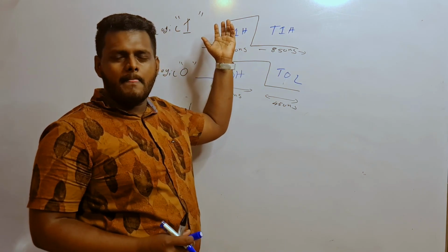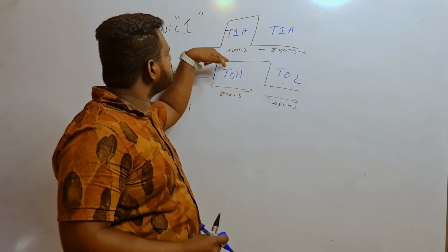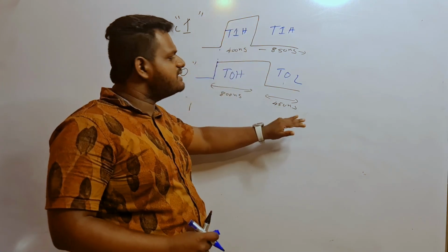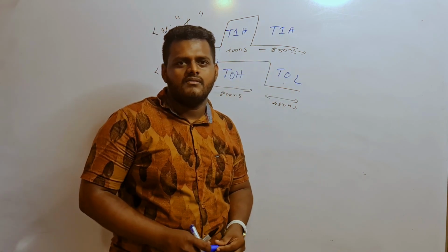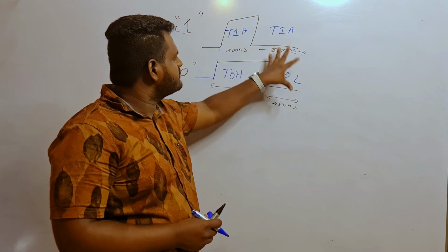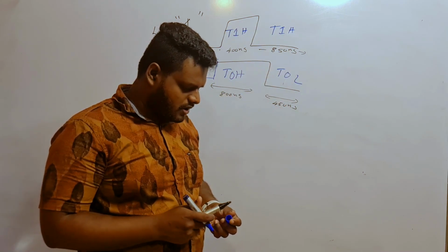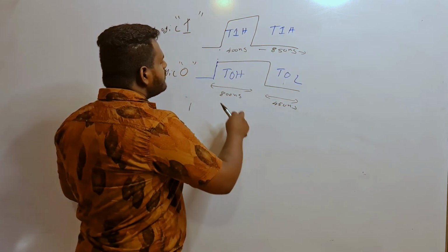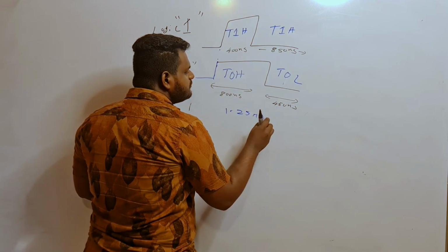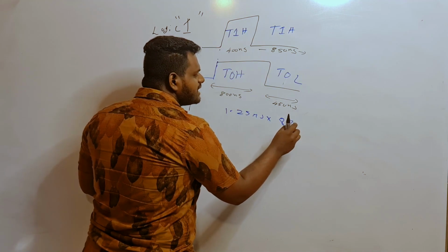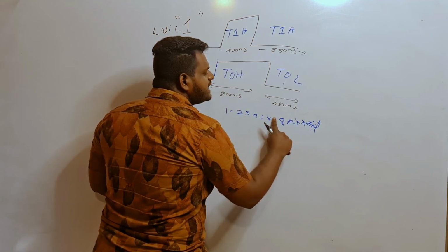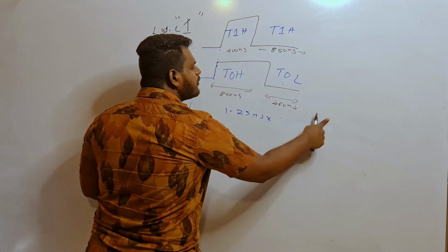At some time both logic levels are high and at other times logic 0. Over the run of this 1.25 microseconds you have your 8-bit data stream, with 24-bit total data.